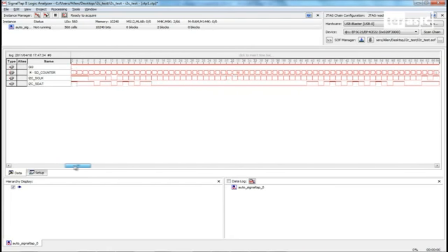And our first call address will go to our slave address, which is A0. So we have 10100000. And since this bit is low, it means that the slave acknowledges our signal.